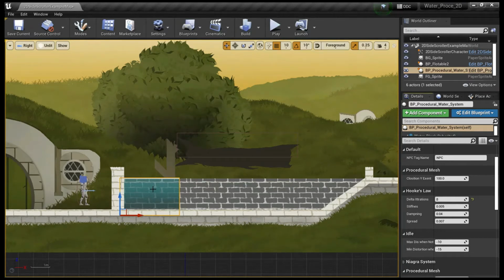You keep in mind this stiffness value. This stiffness value is really important. If you keep the stiffness value to the high end, then the vertice will keep oscillating at the point, and if the dampening is less and the stiffness is more, the vertice will go out of control. So you keep this in mind that the stiffness value is really low.